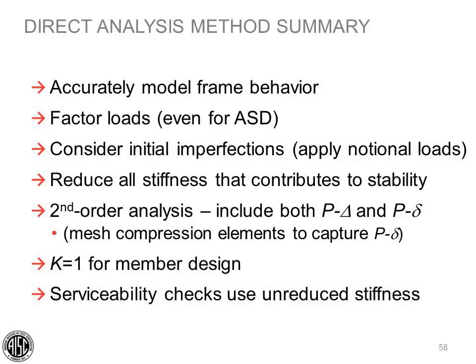Okay, to summarize the direct analysis method, accurately model frame behavior, including all loads and conditions that destabilize the structure. Factor loads for the analysis, even for ASD. Consider initial imperfections, usually by the application of notional lateral loads. Reduce all stiffness that contributes to stability.